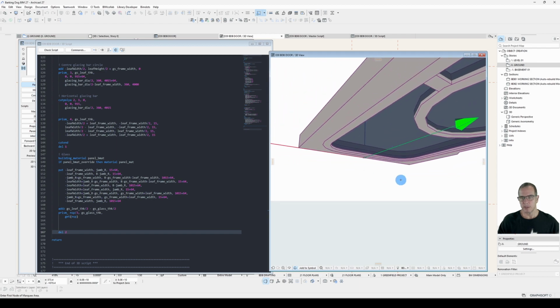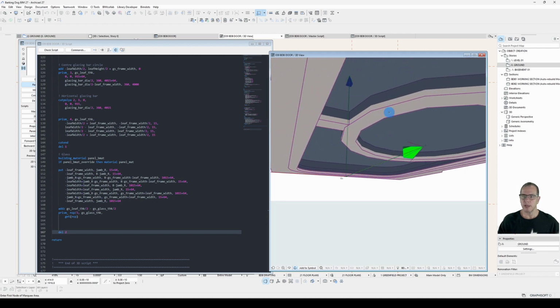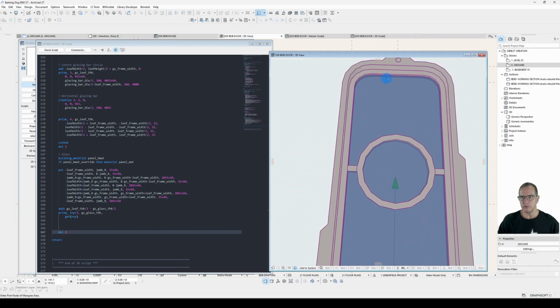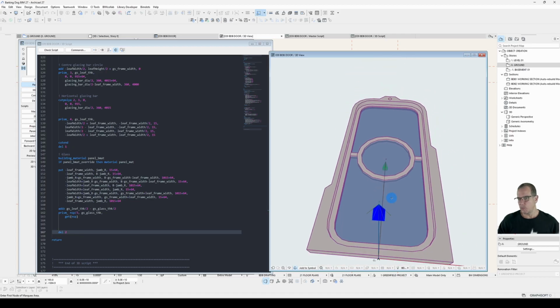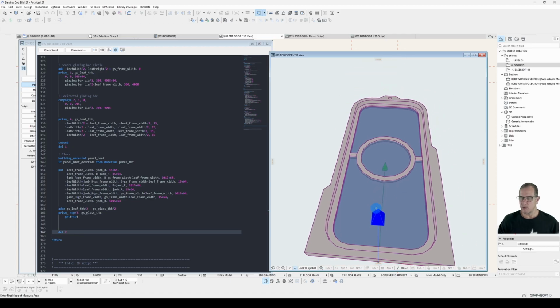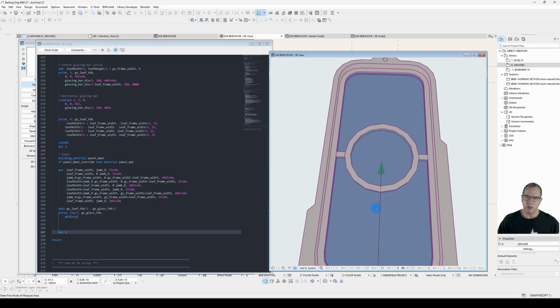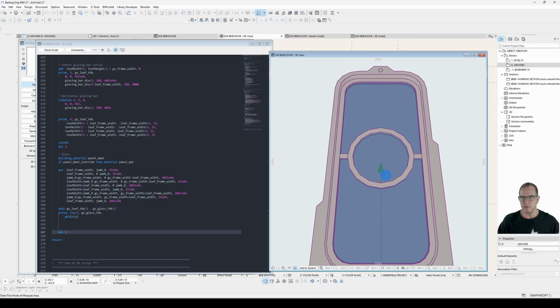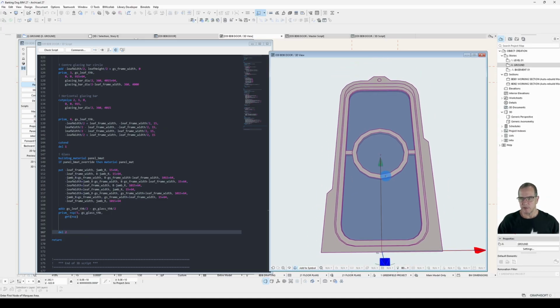Now, by drawing a single pane like that, I've got clashing geometry here. I can go to the trouble of drawing individual panes for all this. You can accept that that's okay to do it like that. You can do a group to subtract one from the other. You can run a cut poly in the same position as the plane to cut this leaf, cut the glazing bars of the leaf, but for now I'll just leave it like that.